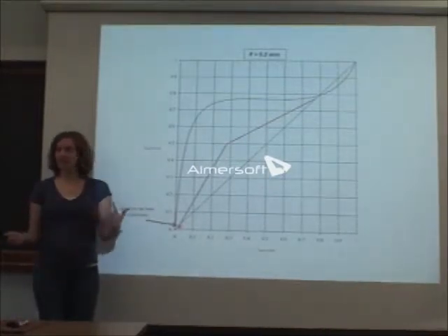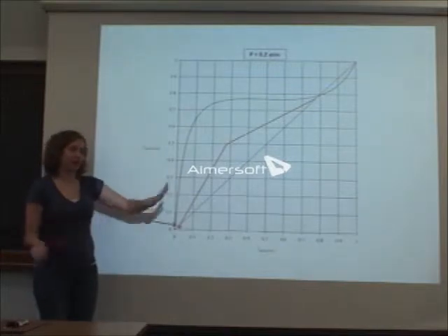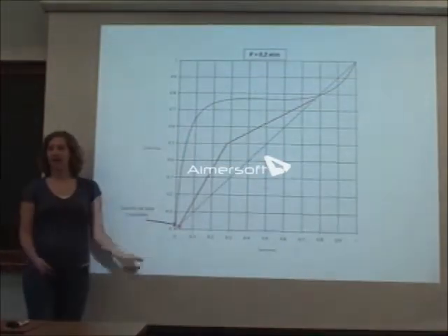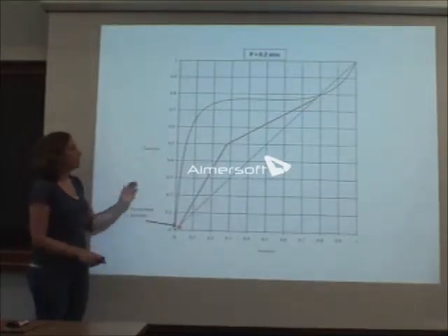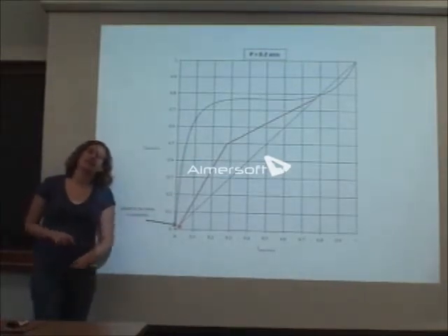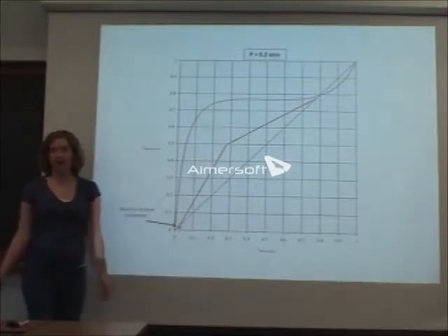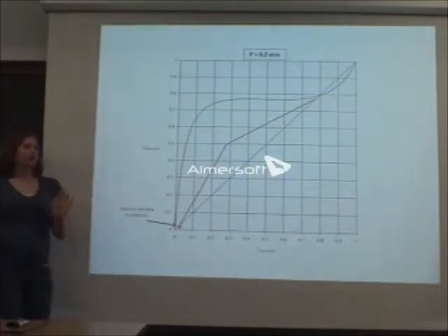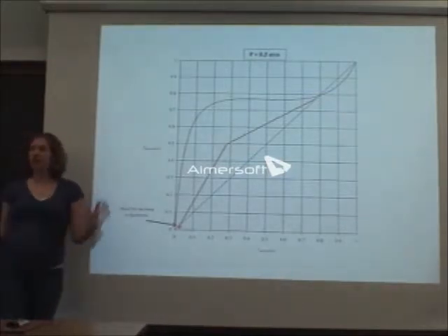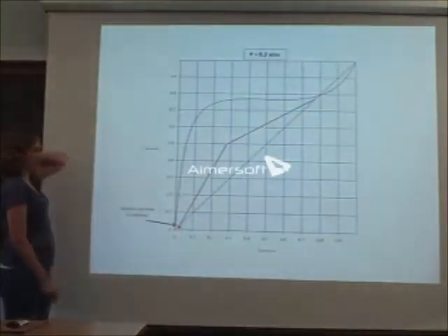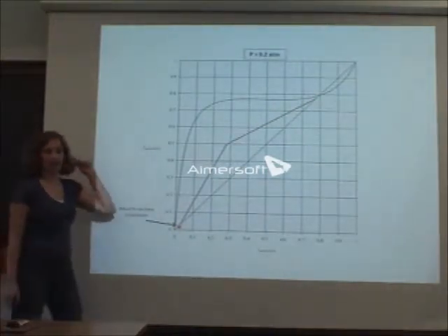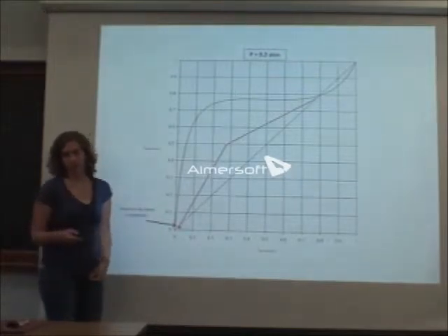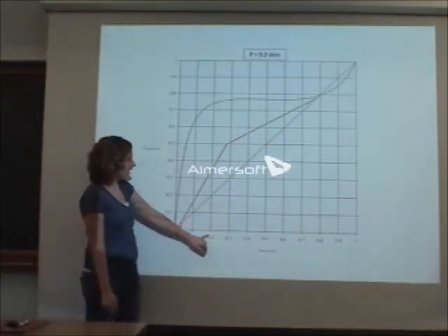So that's kind of inconvenient because we want to take stuff out of our column. So if we're operating here, we're not actually taking things out of our column. So that's not good. So we definitely need operating lines if we want to take stuff off the top and out the bottom of our column, okay? So I put these operating lines here. Another thing we were talking about a lot was the feed composition and where that feed is. So where is our feed in this case? Dan? It said that the feed was like 20% acetonitrile. Yeah, so it's like 20%.